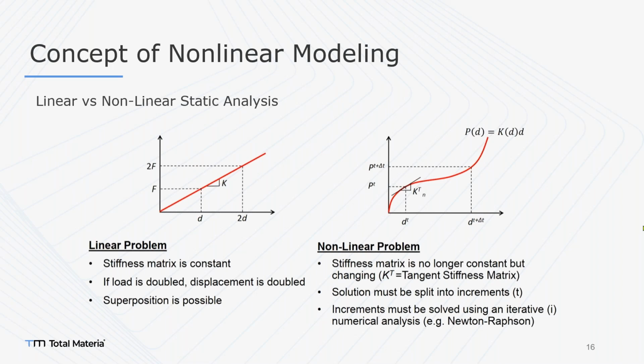Also, there are some kinds of problems that could be an issue for Newton-Raphson, which are bistable structures. In bistable structures, as you may know, there's a sudden softening. Because of that, Newton-Raphson will have convergence issues. So in that case, the arc length method is used. It's not only for material causes, but also for snap-through analysis, for example. The whole analysis procedure can use a linear material model, but the snap-through is still a problem, so there should be a softening force here.